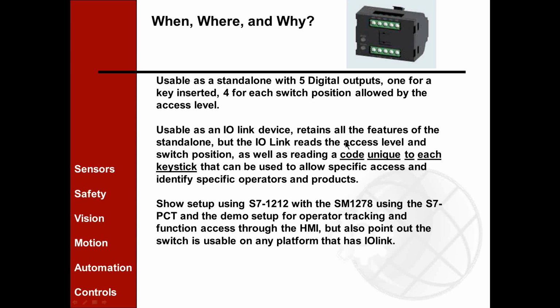It's usable as an I/O link device and retains all features of the standalone, but the I/O link reads an access level, switch position, as well as the unique code of each key stick. I think that's one of the most powerful things this has going for it. It can identify operator to operator to operator rather than just what the access level is.